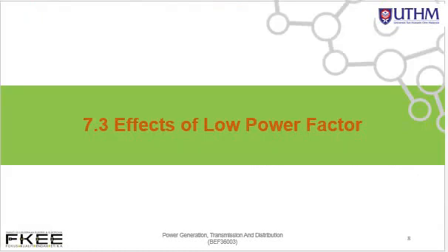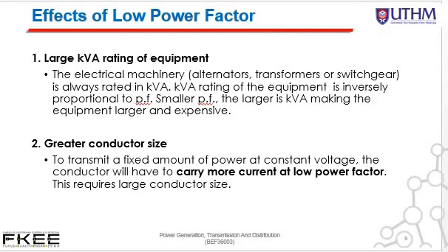There are several impacts when the power factor is low. The first one is that we need a large kVA rating of equipment. As we know, electrical machinery such as alternators, switchgear and transformers are always rated in kVA.